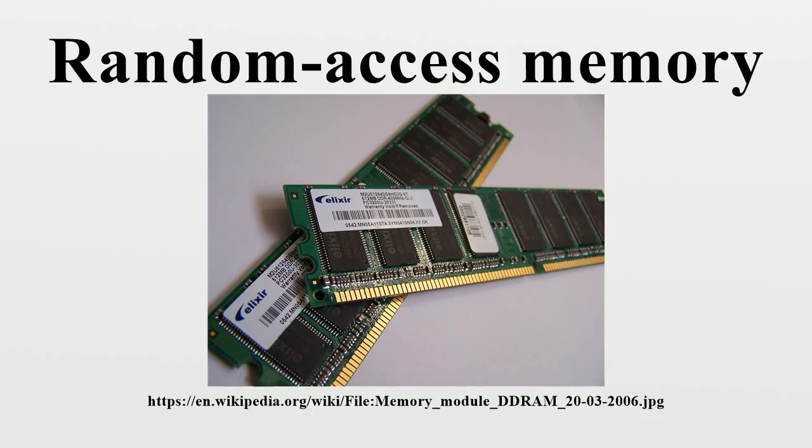Shadow RAM. Sometimes, the contents of a relatively slow ROM chip are copied to read/write memory to allow for shorter access times. The ROM chip is then disabled while the initialized memory locations are switched in on the same block of addresses. This process, sometimes called shadowing, is fairly common in both computers and embedded systems.